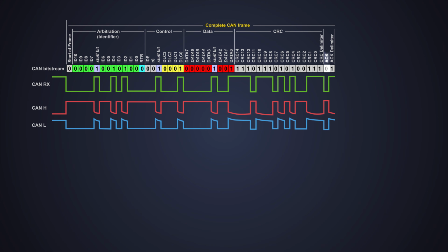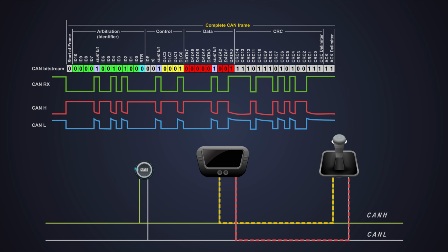When the receiver receives the accurate message, then the receiver has to replace the upper bit with a dominant bit, indicating successful message transmission. If the receiver keeps this logic high, the transmitting node retransmits the message according to arbitration. This acknowledgement is the same as the acknowledgement mechanism in I2C, where other devices on the bus are telling the transmitter, hey, we got your message, or we got incorrect or no data, if they do not turn this bit to dominant bit.